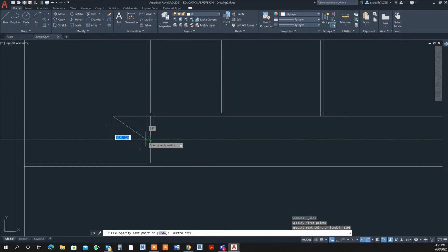Okay, I'm just gonna stop here. So I need my door to be 1.2. So I'm gonna use the offset again, 1200, and I'll offset this line. Okay. Now this is the opening of my door, so I'm gonna use the trim. Okay, so this is just the opening, and also I don't need this line.